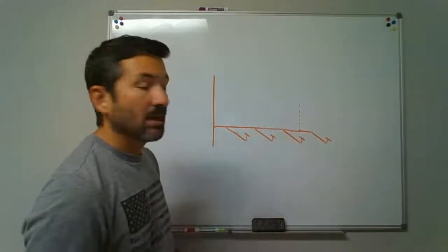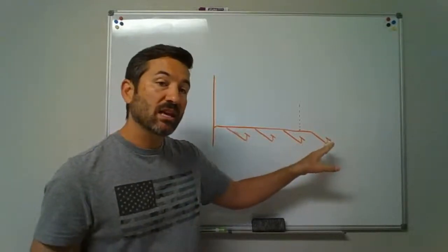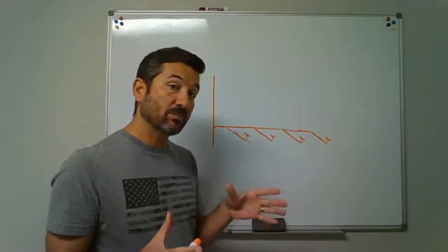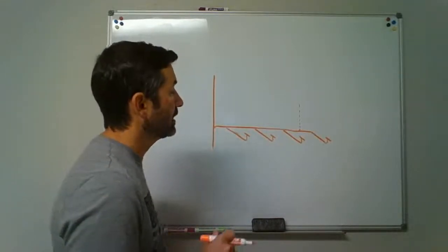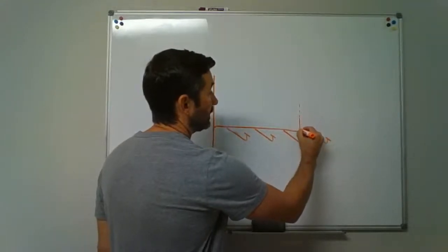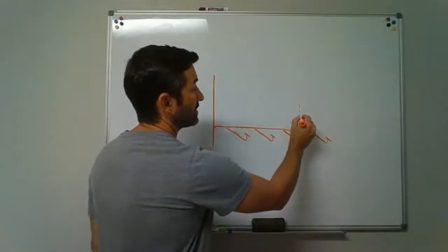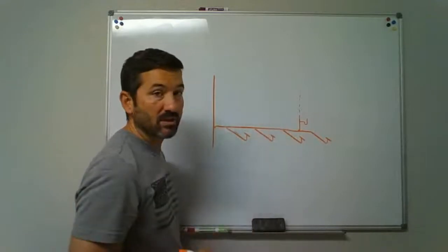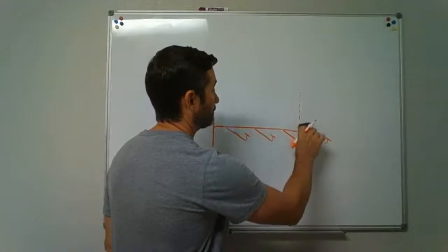Now, I don't know if you've seen some that might have regular stalls, and at the end, a handicap stall, and it might be a big one. And in that handicap stall, they might have a sink, so it's all got its own separate sink right in that one. So what it's saying is I cannot tie the sink drain into this and come out and put a sink drain and say the sink drain is going to have a vent coming off of it. I could not plumb it this way and call that the circuit vent. Okay, it's got to tie in separately.